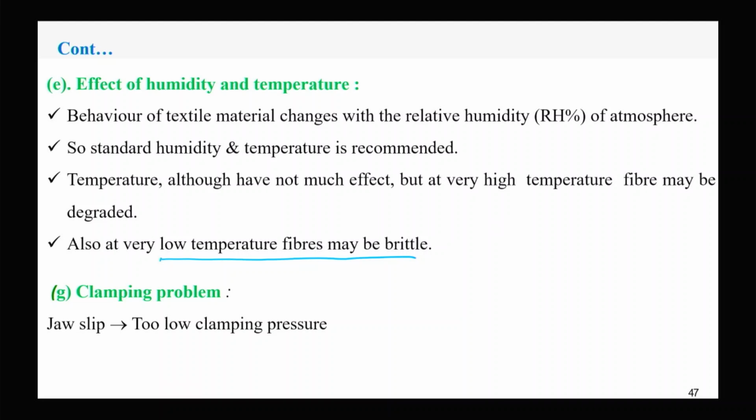And clamping also: for the same material, if we clamp improperly, the result will be different. As I mentioned earlier, this is the standard stress strain behavior, and if we clamp loosely, there is jaw slippage and the stress strain behavior will be like this.